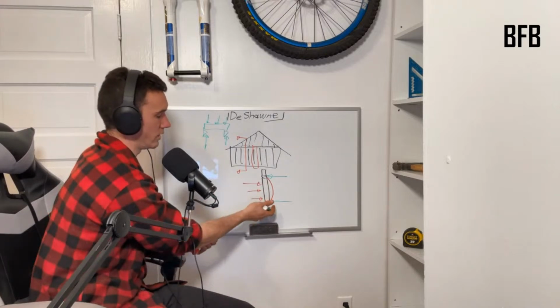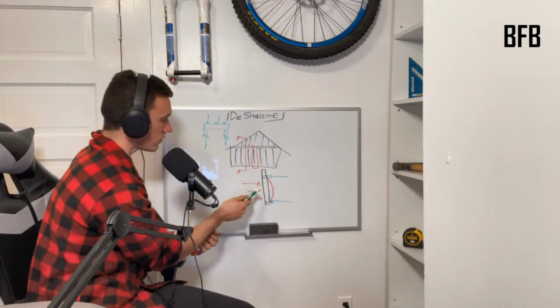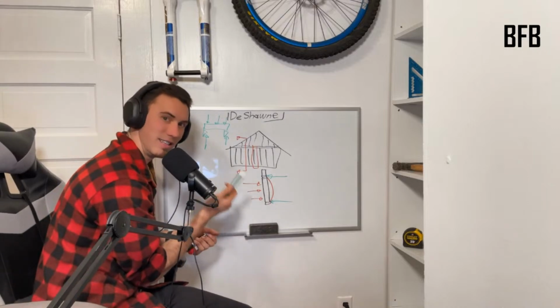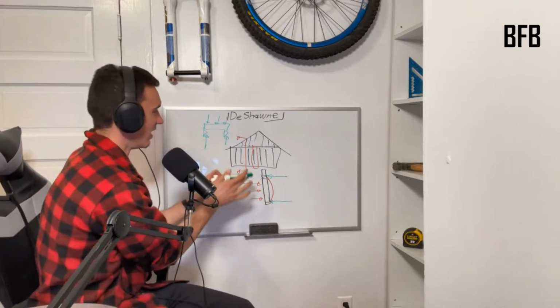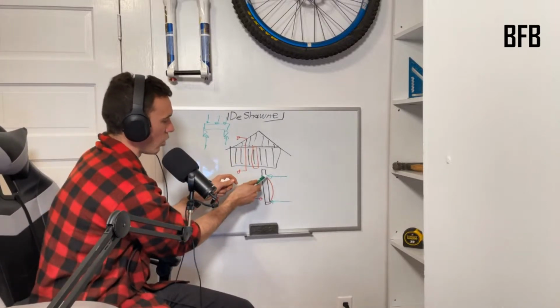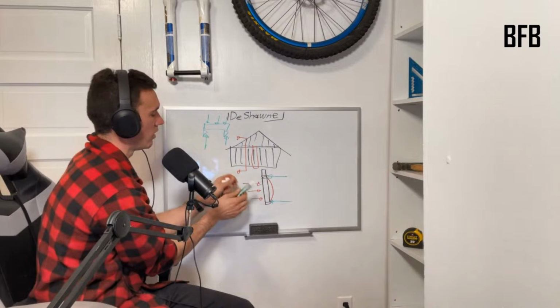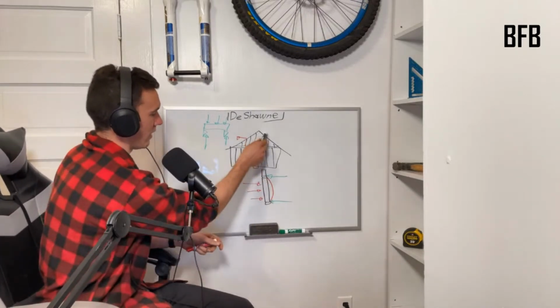It's not going to move. It's resisted down there. So what on earth is resisting it up here? Well, that is the ceiling diaphragm. I know. This is really exciting. So the ceiling diaphragm is pushing back on this wall plate to keep this wall from hinging in towards the house. Now, here's the other problem that people have when they have an attic and a gable wall like this, right?